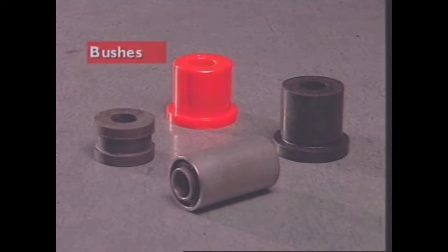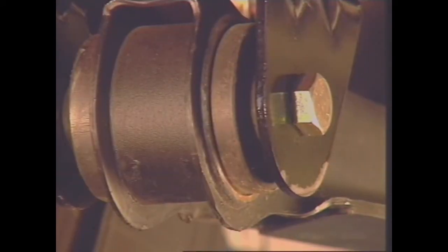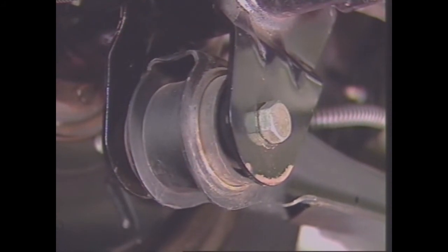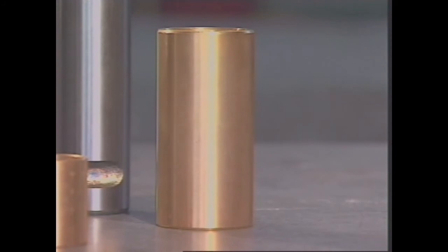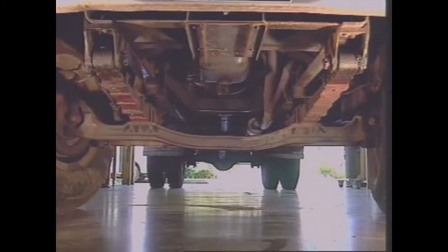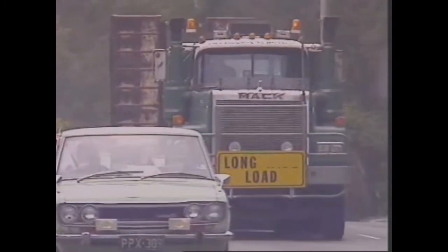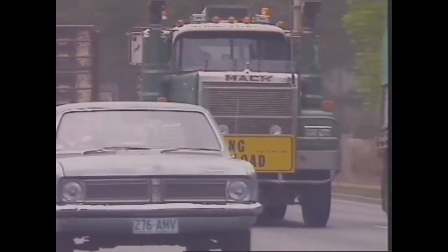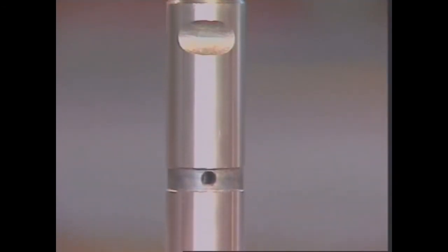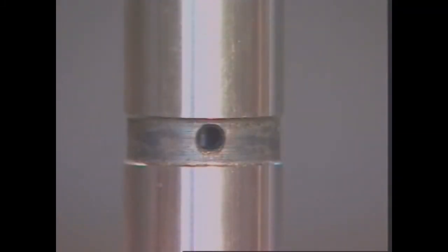This section examines suspension system bushes. Bushes act as bearings at suspension fulcrum points to allow for movement of the component while maintaining its alignment. They can be metallic or made of rubber, nylon or urethane. In commercial vehicles, metallic bushes are commonly used as shackle bushes for leaf springs. Any force applied to the bush acts through it to the body of the vehicle, which results in a harsher ride. The mounting pin on a metallic bush is usually drilled to allow for lubricating the bushes.